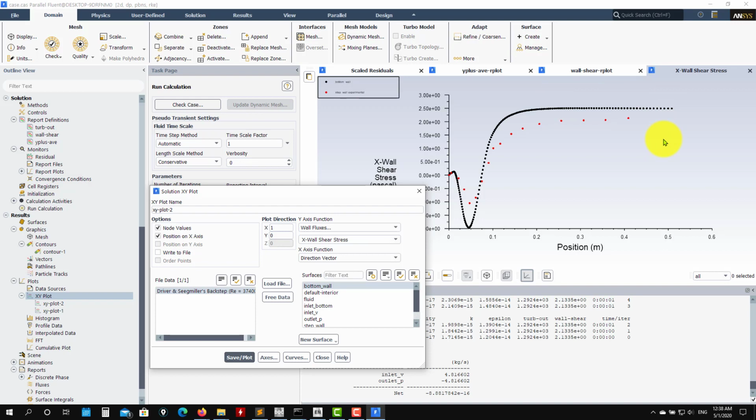You can try many iterations and different methods, and you won't get an improvement. Even if you refine your mesh, you won't get a clear improvement in your solution. Here is a chance to choose a much better boundary condition, so let's use a profile.